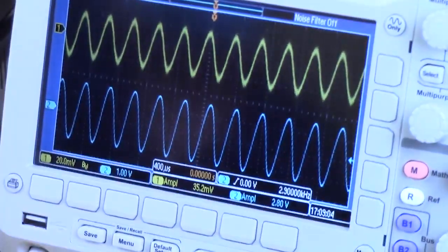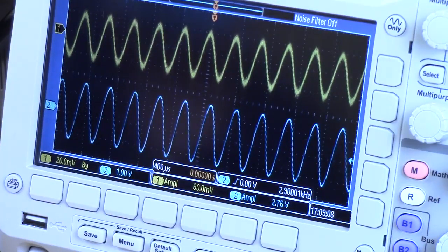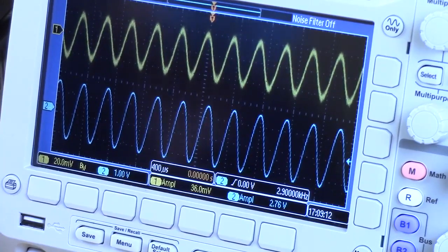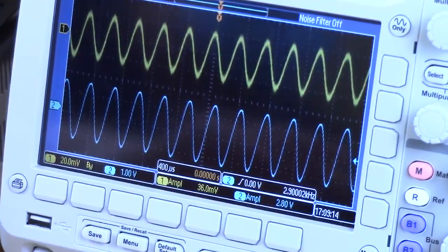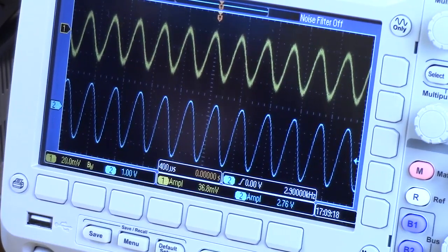Technically, this is 3 kilohertz. Technically, we should be more like 30 kilohertz to get fully into midband. But this says we have a pole due to CE. Remember, C1 and C2 are moved out of the way now. This is CE alone. We have a pole of 2.9 kilohertz.